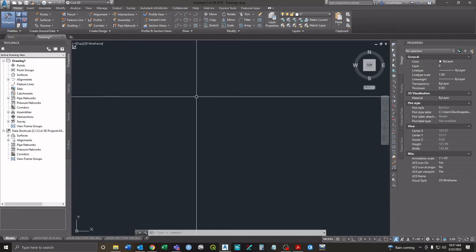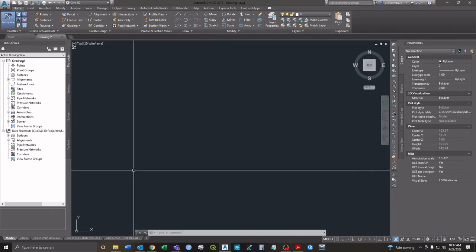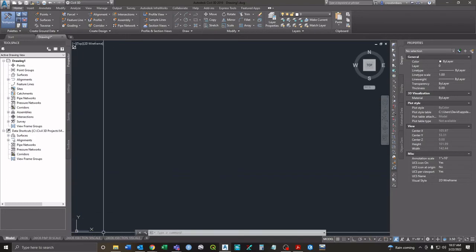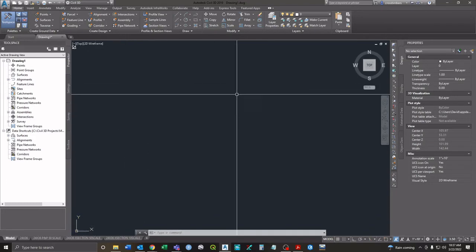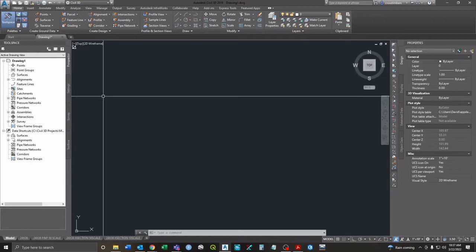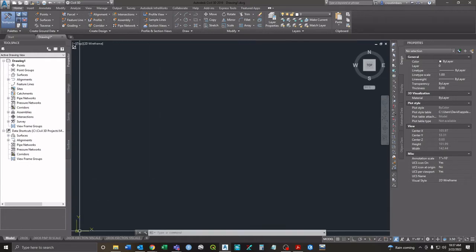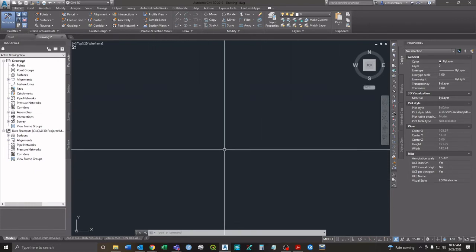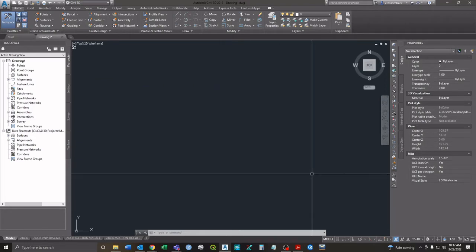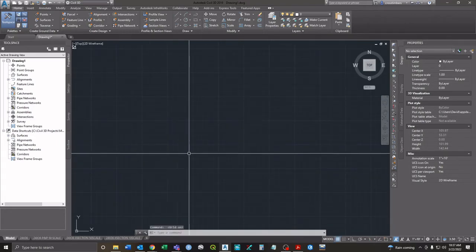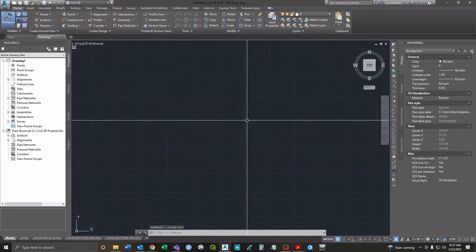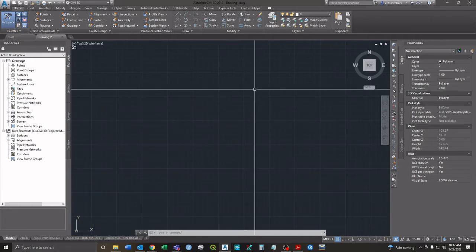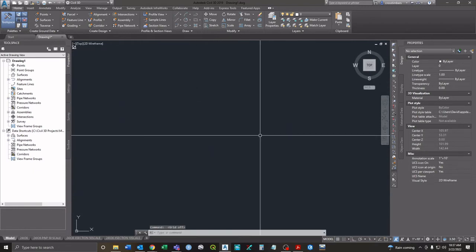Basically, this lives in 2D space right now. So you see down here you've got your XY, and everything we type in is an XY coordinate. If you don't set any coordinate system, then this point in the corner here is 0, 0, so 0 in the X direction, 0 in the Y direction. Everything you draw sits on a grid, which I'll show you. If you hit F7 you can get this grid, but it's not useful. But that's the grid in this space.